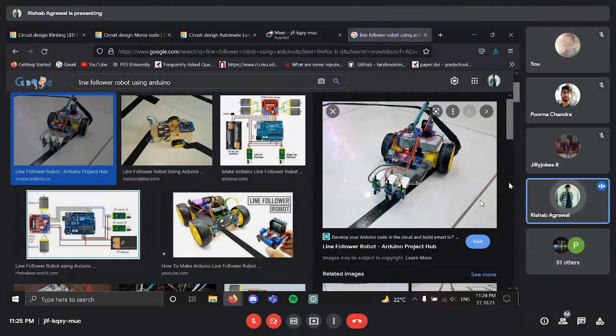So between 0 and 255 of the motor speed corresponding to what the LDR value gives, you can give that also. And for your implementation part, just assume that the LDR value is from 0 to 450, because you're not using hardware. You don't have any way to test what the LDR values are. So 0 to 450 is good enough. And using the map function or the indirect proportion, you change the speed of the motor.